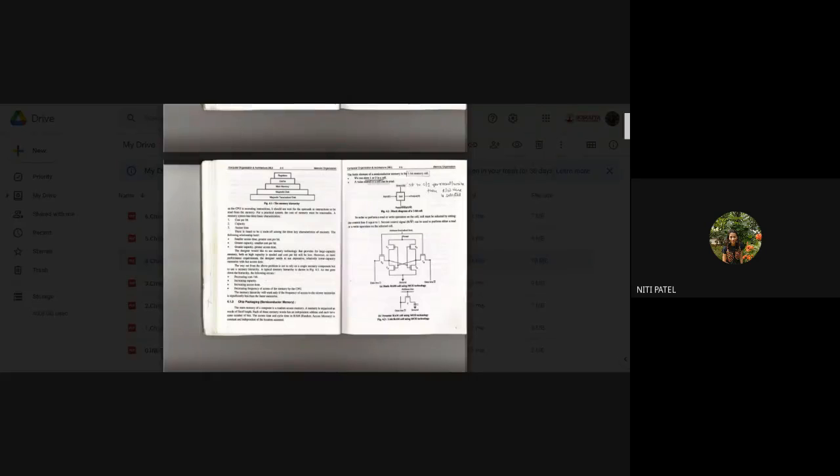What is happening in the input line is that whatever input a user gives to the system is taken one by one through that line. Whatever output that particular cell generates is taken out from the output line. Now, what does the select line do? The select line is set to either 0 or 1. Depending on that, your read write signal gets activated. When select is 0, read write will not do anything. But when the select line is 1, read and write will activate and start performing both read as well as write.